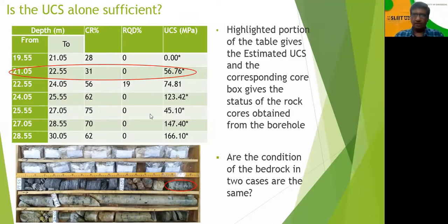Whether the use of the UCS is reasonable, I have a question here, because now most of the material in the void spaces has been washed away. So what is left behind, we are obtaining the strength of. Of course, you are using the RQD value, that is true, but the use of this UCS alone we have to look at again. So that is another disadvantage of using that particular chart.